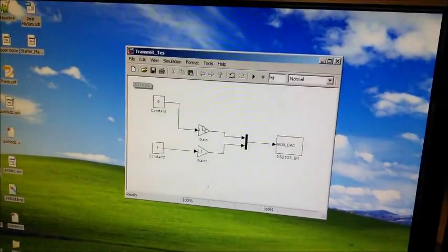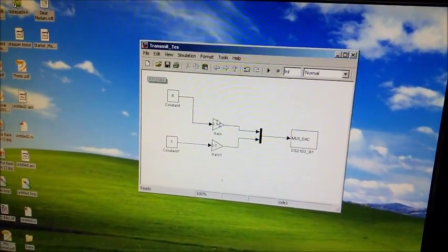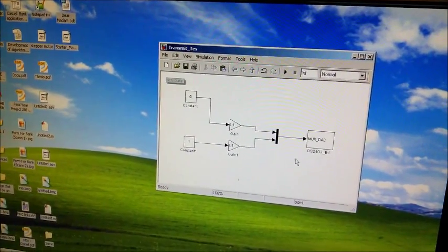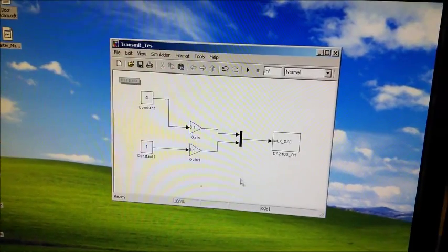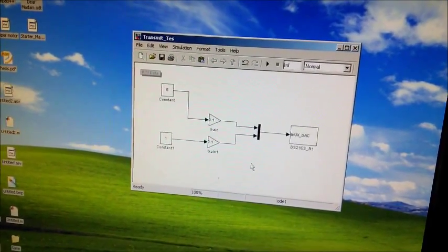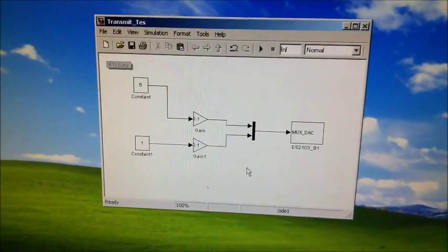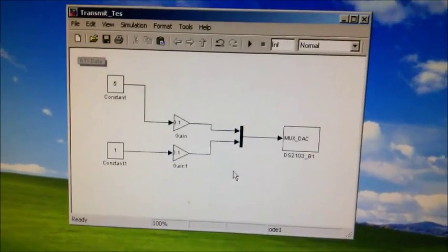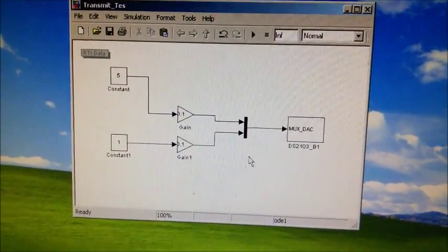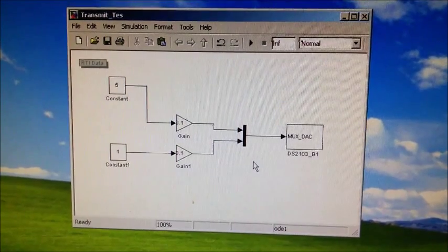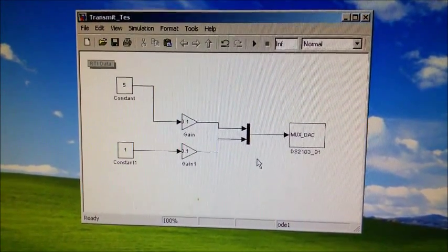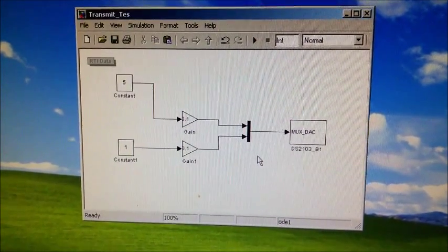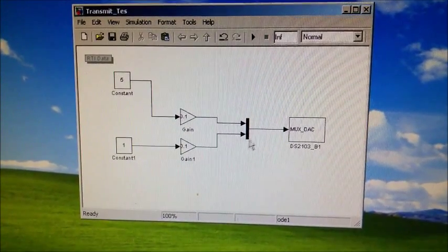And in case of the speed, it starts from 0 volt, and if you keep increasing the voltage from 0 to 10, when the 10 volt is transmitted to the pump, it will rotate at the highest speed, which is 220 revolutions per minute.